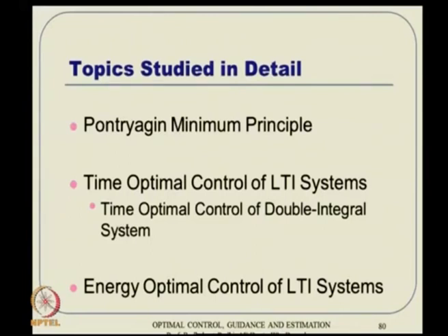Whereas energy optimal control, where you want to minimize a quadratic cost function of the control variable, is much more benign and naturally leads to something intuitive. As long as the control is within the bound, you apply the regular value, and the moment it goes beyond the bound, you apply the bound value. That is possible only when we have this nice quadratic cost formulation in the control variable. It's called energy optimal control.